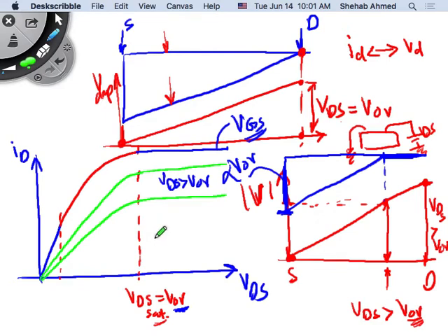But after the compression and so on, would there be no electrons to flow? No. The free electrons are still there in the channel. You still have channel thickness. You pinched, but you still have an electric field due to VDS. The VDS electric field is now a stronger electric field. It will see the electrons in the channel that was pinched further away, and will pull them through. It will pull them through, but it will be hard. That's why it's a higher impedance to the current flow.